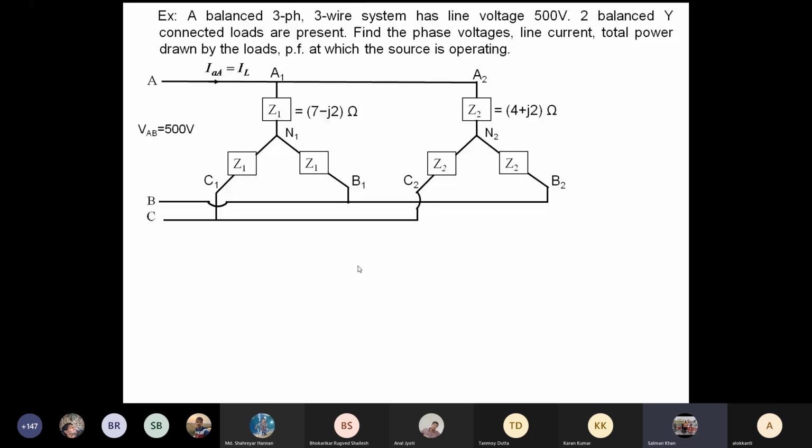In the slides you have mentioned that three phase three wire was delta connection and three phase four wire was star. Three phase four wire is star, but you may not even use the fourth wire. Star is such a thing that the fourth wire is available, but you may not connect it. The fourth wire may not be made available to the user.